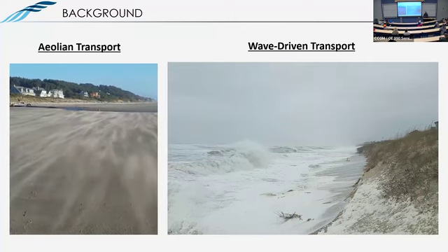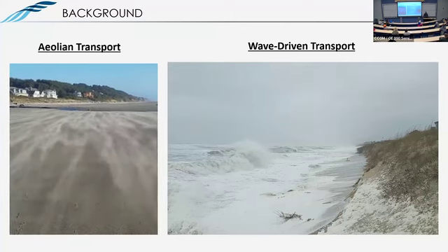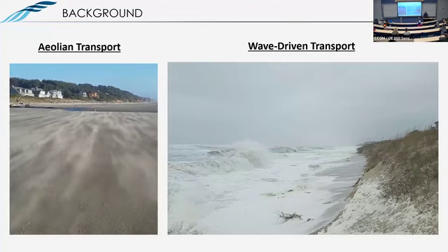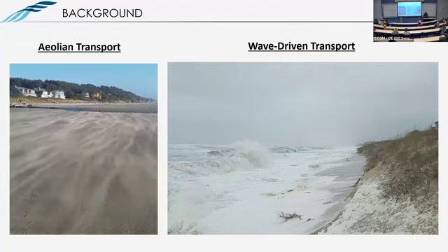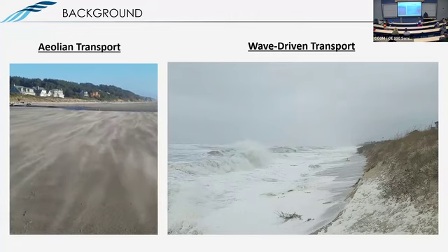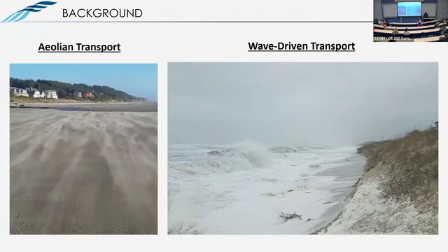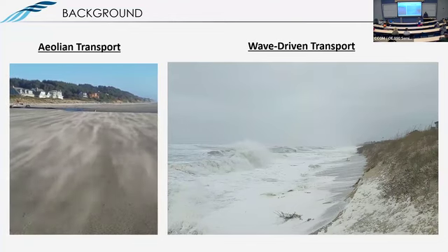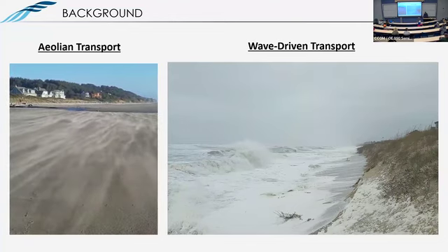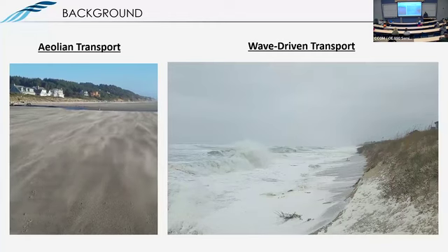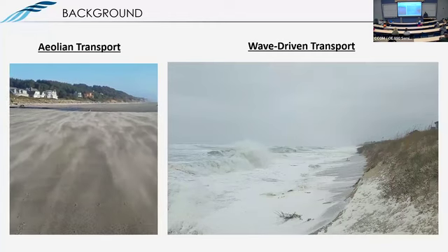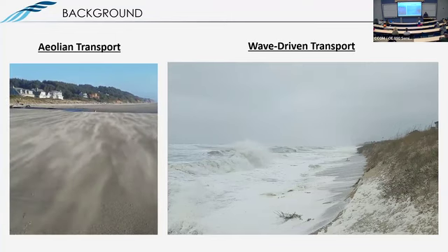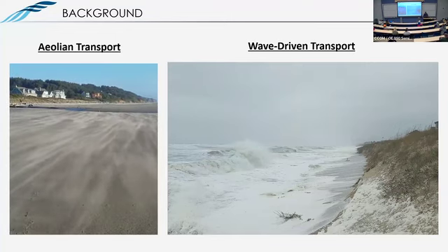The work that I didn't talk about is that we're doing a lot at the moment in terms of parameterizing vegetation effects on the shear coupling with the bed shear stress field. That's a lot of ongoing work using process-based experiments, mostly in the field, a little bit from the lab, to inform new parameterizations in higher fidelity tools, where we're trying to take a lot of these effects, like adding sand fences into morphological models and species-dependent vegetation effects.